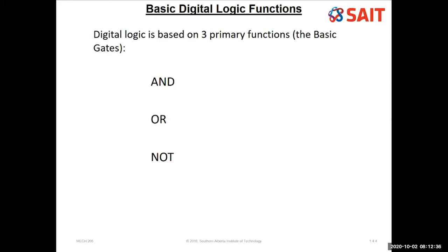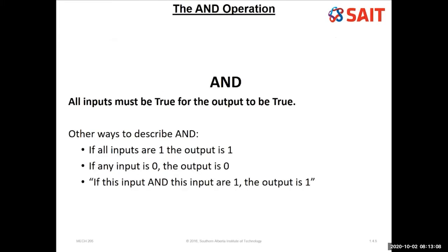So these are your 3 basic primary functions, and everything can be built from these 3 primary functions. It's not a very efficient way of necessarily doing it with these 3 basic functions, but it is possible to do this. So certainly when I get something like a pneumatic computer or something like this, typically I'm using pretty much just these 3, ANDs, ORs, and NOTs. The other ones we'll talk about later are far too complex in a pneumatic system, very expensive. So every decision can be really made on these ANDs, ORs, or NOTs in successive decisions.